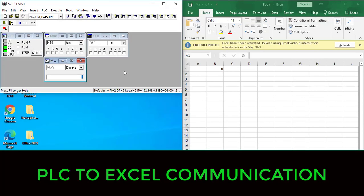And here on the runtime, you can see the speed will be updating over here, and I'm going to insert the M0.0, and you can see that it is 1, and by clicking it is 0, and by changing the speed you can see 44. I'm hitting enter. You can see it is 44, and if you want to change from here, I'm going to change it as 68 and hit enter. You can see the 68 will be updated.